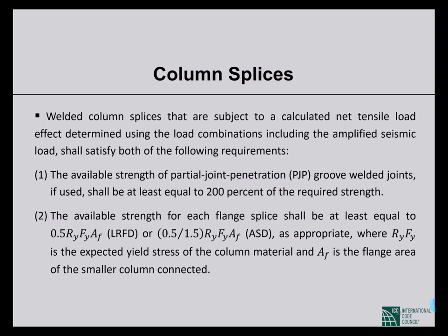The available strength of each flange splice shall be at least equal to half of RyFyAf, that is flange area multiplied by yield strength multiplied by expected strength factor, or there is, for ASD, another amount as appropriate, where RyFy is the expected yield stress of the column. Okay, so here we are becoming conservative in a different way.